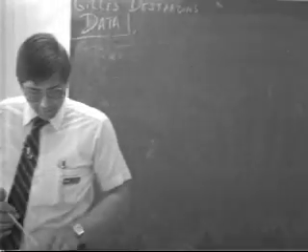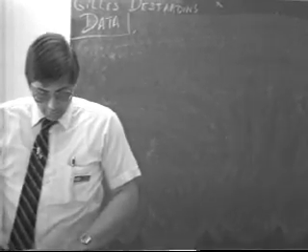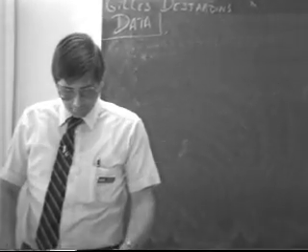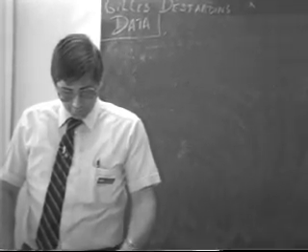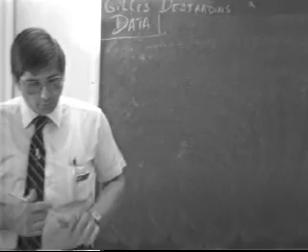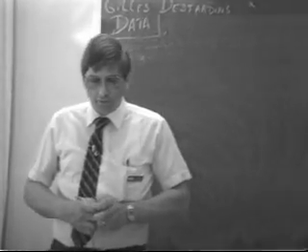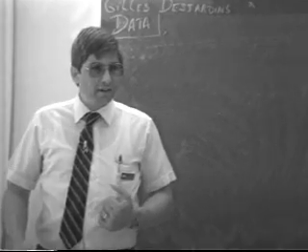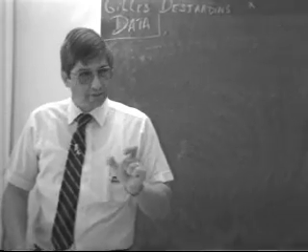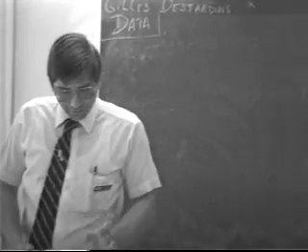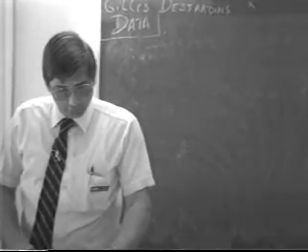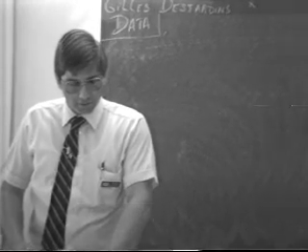The test program itself, what does it do? It loads a 256-step staircase into each lookup table. Each table will contain the following information at the end of load. Table addresses 0 to 7 will contain 255 for data, so you go through 8 addresses. Addresses 8 to 15 contain 254, and so on, up to 2047, which contains a value of 0.